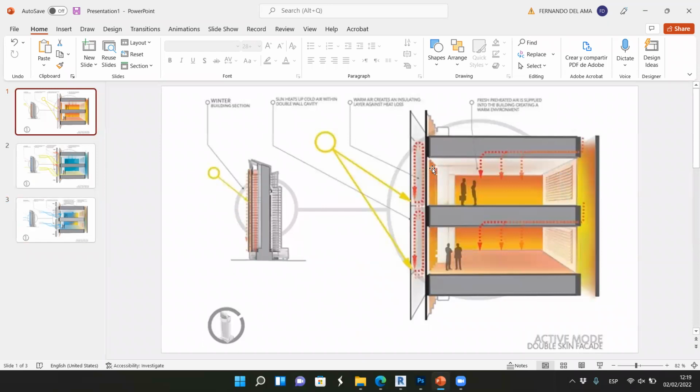this is it. Okay, so we have a transparent element here. We have the first curtain wall here, and then we have another light curtain wall here outside. So this is a double skin, and we have a buffer space. It's not a corridor, it's nothing. We can have like 3 feet from this first line to the second line. But that's interesting because depending on the weather outside, we can have different strategies.